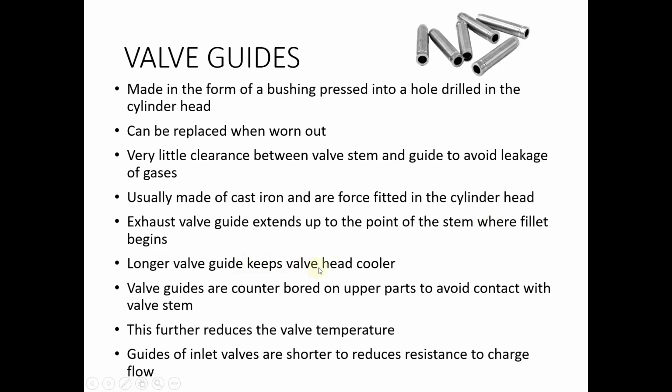A longer valve guide keeps the valve head cooler. The valve guide also has the function of reducing the valve temperatures, because it ensures that the upper portion, that is the stem region, is isolated from the high temperature. It is insulated from the high temperature due to combustion. So it ensures that the other portion of the valve is maintained at a sufficiently lower temperature.